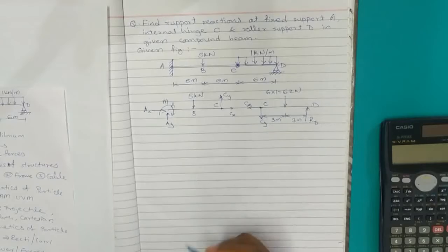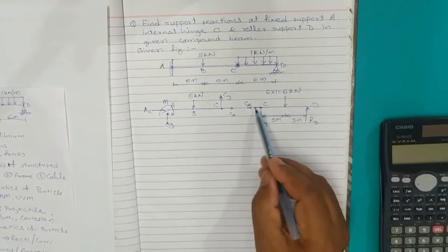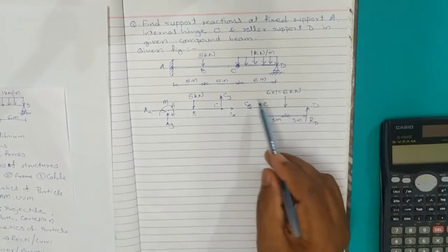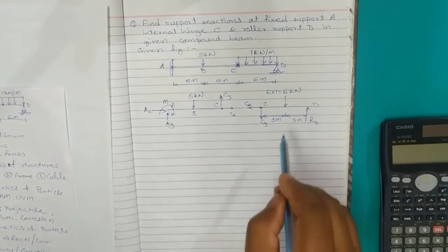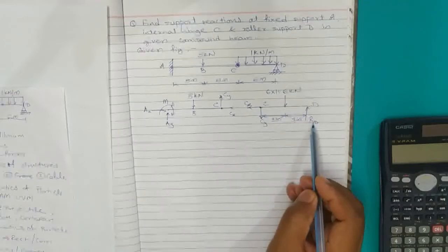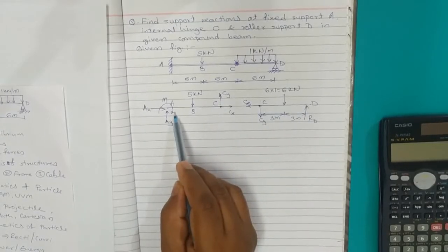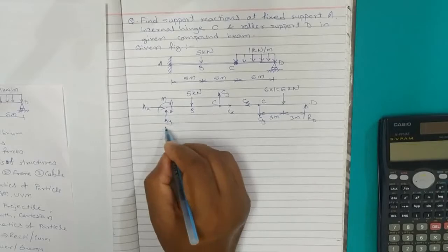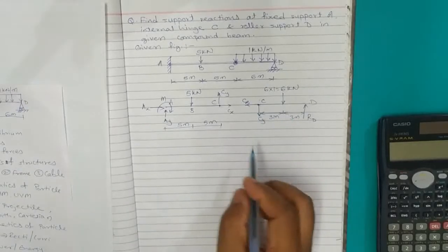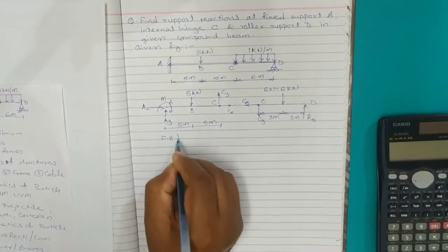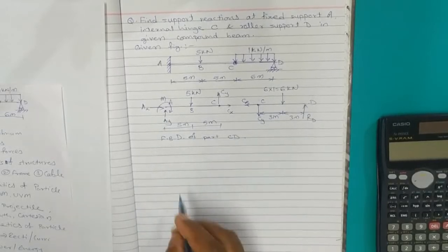So these are the forces and the FBDs of the two isolated members of the given compound beam. Here in CD we can see that Cx, Cy and Rd are the only three unknowns, and we can solve it easily. So we are going to first solve the FBD of the member CD, and then we will go to the other member ABC. Let me show these dimensions, and then we will go for solving the FBD of CD. Let's solve the FBD of member CD first.